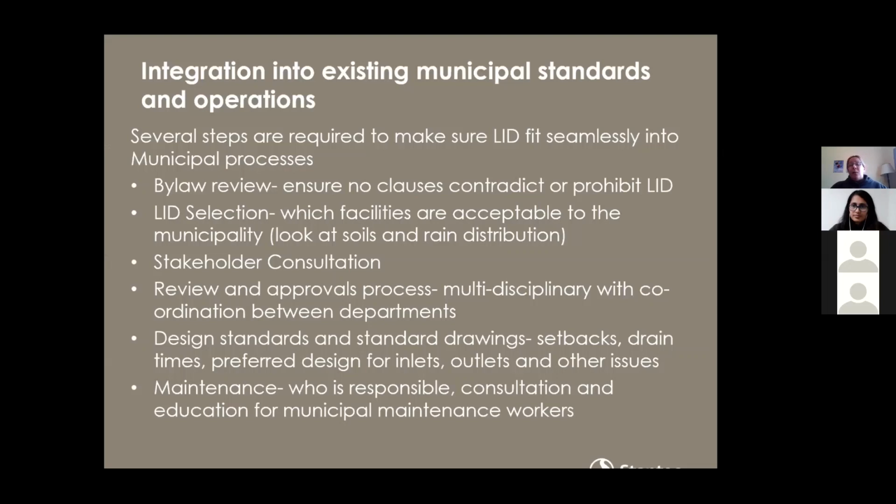You also have to look at what facilities are acceptable to each municipality. The types of facilities you choose may depend on your rain distribution, what types of soils you have, and really what you want your program to look like. If you're in a very urban area, you could have a lot of underground facilities that don't take up a lot of room, whereas if you're in a more rural area, you might want a lot of at-surface facilities and more of the garden look.